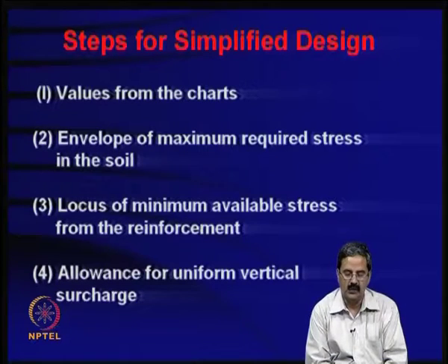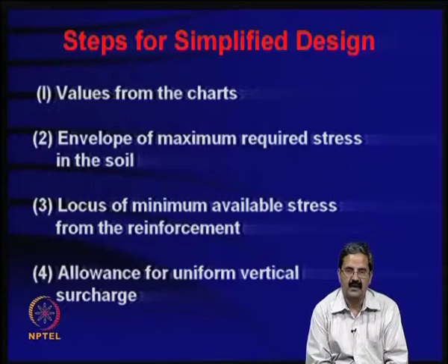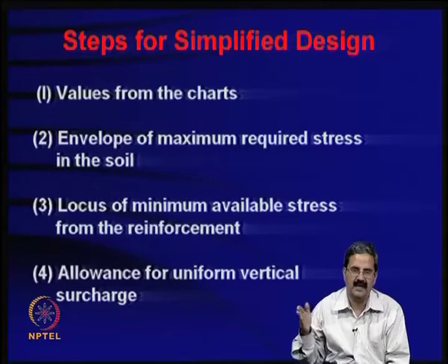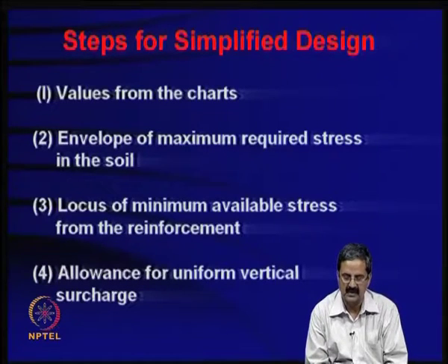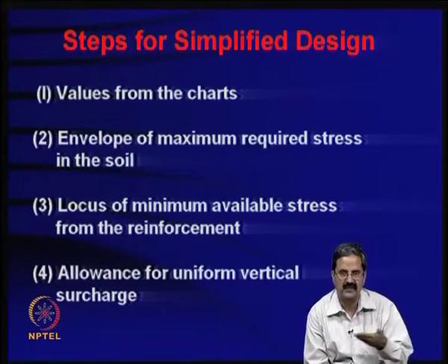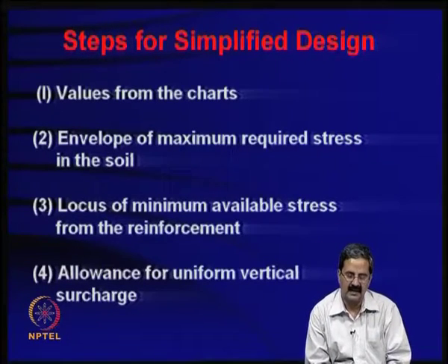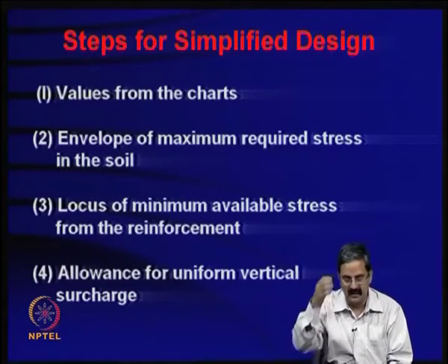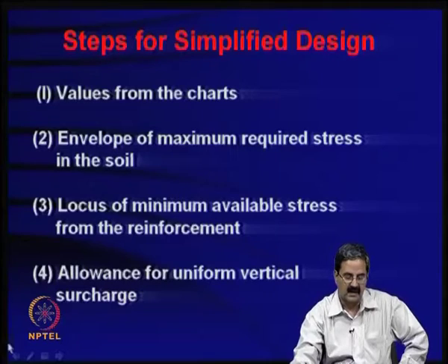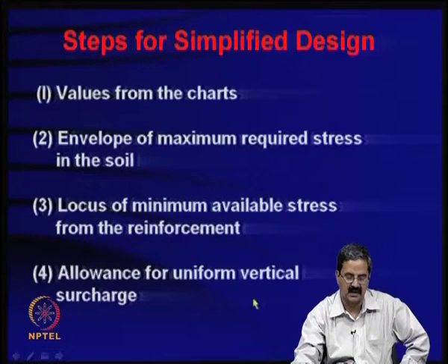What is the reinforcement giving? Something is required: the earth pressure at any point is calculated in terms of Ka gamma H, but what can the reinforcement give? If it is a very stiff reinforcement, it can give inward shear stresses. There is also a surcharge and other things, and one can even consider some of these things in the design.